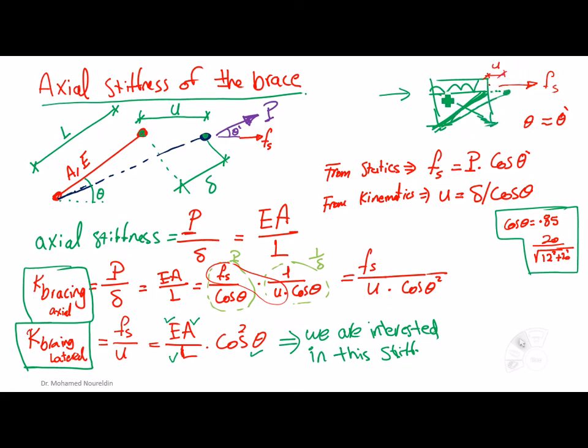But I didn't mention the buckling of the other one, which is going to be definitely in compression, right? Why? Because we are assuming that this rod is not going to resist anything in compression. It is a rod 1 inch diameter. Can you imagine? So buckling will not work for us, and if there is resistance from buckling, it would not be that big. It is going to be negligible.